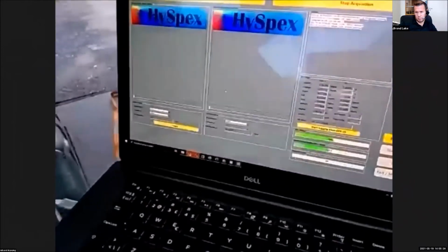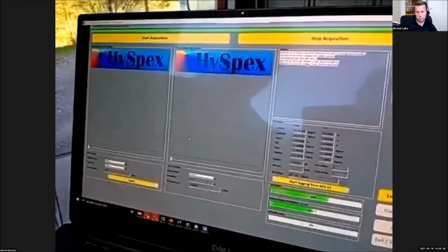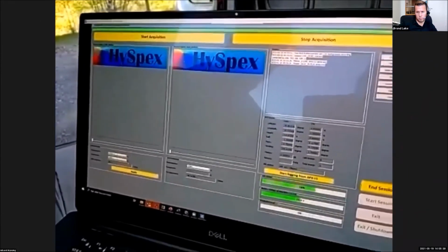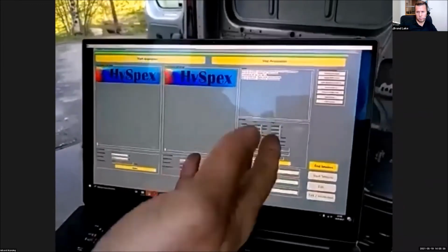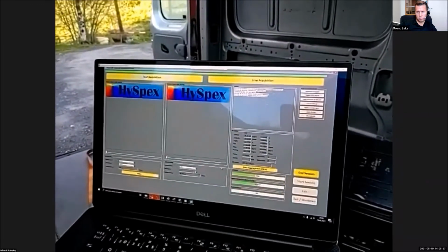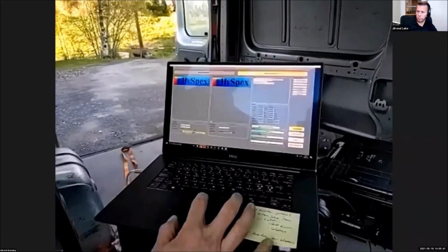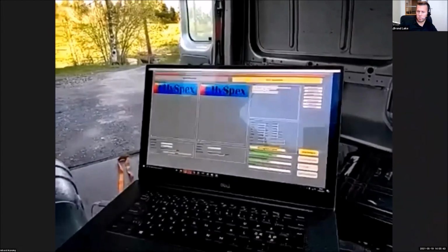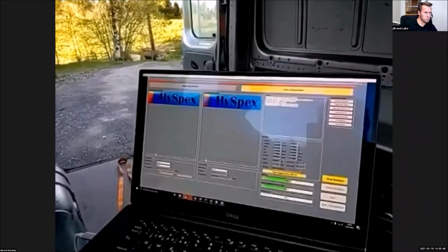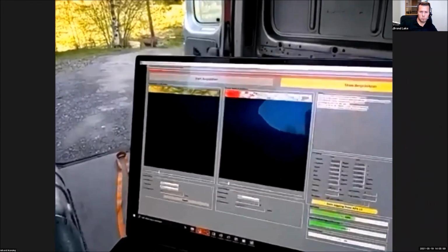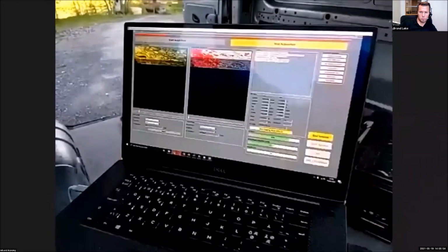With the remote desktop to the mission computer inside the system, we adjust the exposure times and the frame period relative to the speed, where you have data from the INS, and then we start and stop the acquisition. We can do just a test acquisition now in the beginning. It's a bit dark, so I'll put the gain up on the preview here. It's actually saturated. I put it in high gain mode.